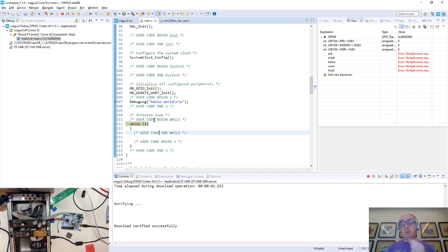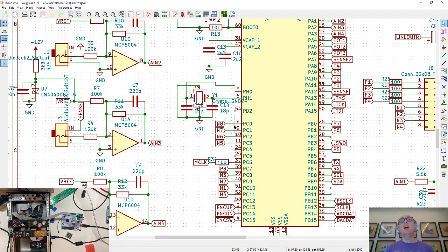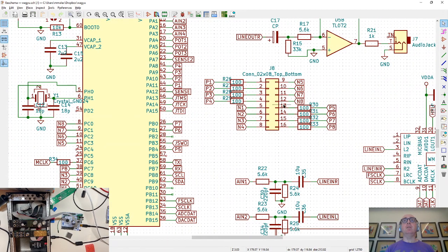Okay, so let's do some GPIO action. We've got some LEDs on the front here, and let's light an LED. So we go and look in my thing, and I have pins 8, 9, 10, 11. I labeled them as, so the LED matrix is basically a classic matrix of rows and columns, right? And for some reason, the pinouts are bizarre. They go in these crazy orders, like 1, 2, 3, 4, 1, 2, 3, 4. Sort of, I think it's designed so that if you rotate it 180 degrees, it doesn't get back to front.